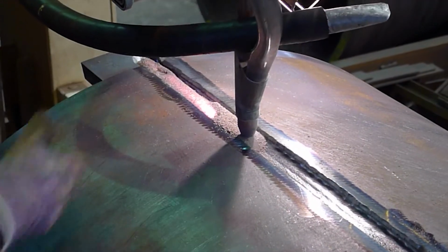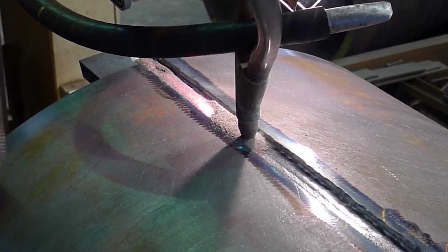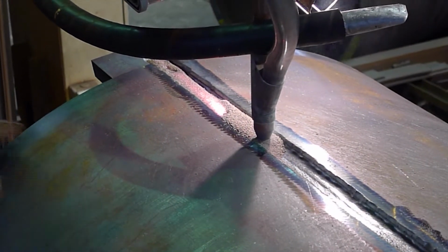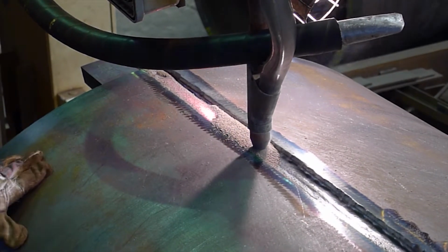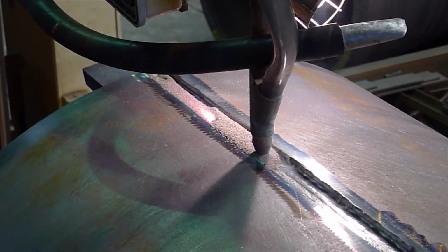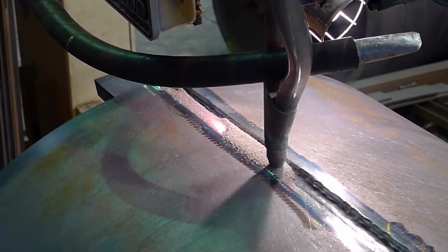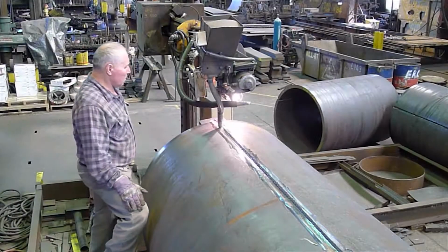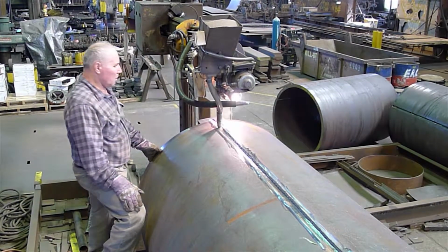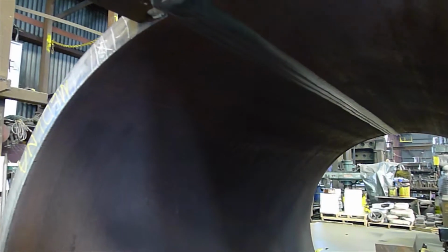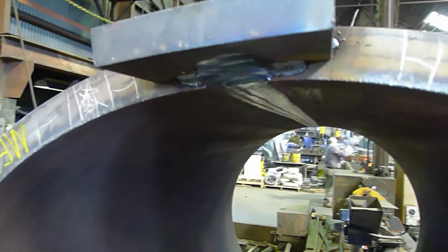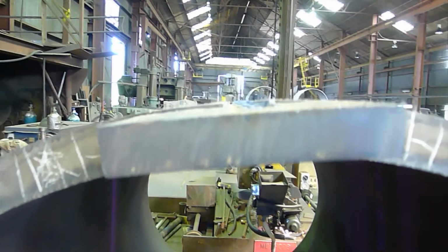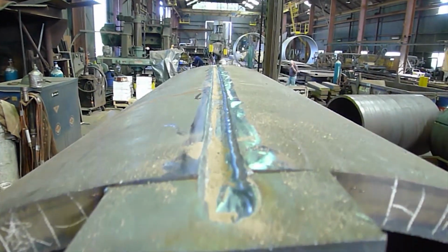In this case, 50mm steel plate has been rolled into cylinders. The join is being welded and filled by up to 7 runs of the welder. The consumable electrode in this case is 4mm thick, the thickest gauge available on this type of machine. Here we can see a completed weld on the inside of the cylinder and a partially completed weld on the outside. The extra piece is called a runoff plate and will be removed at the completion of the weld process.